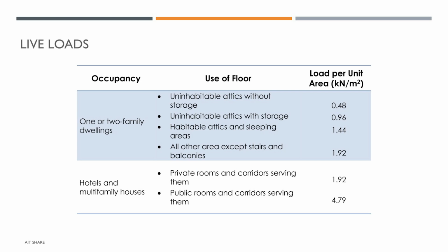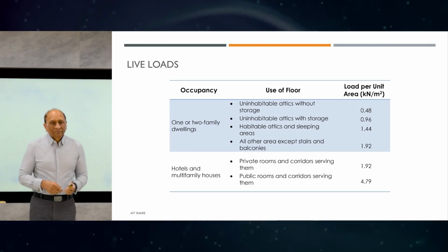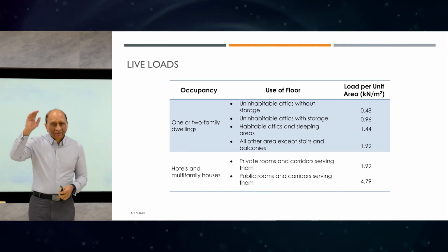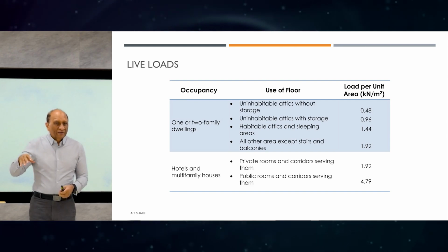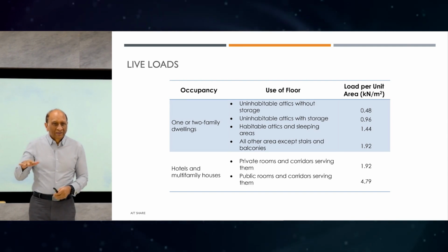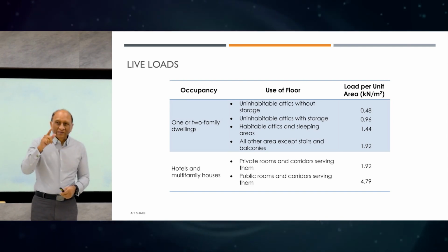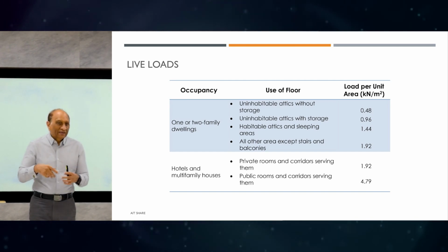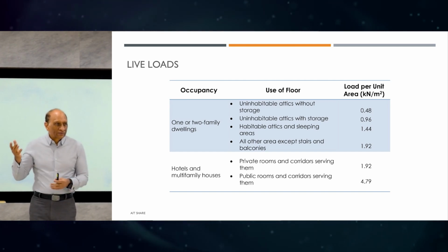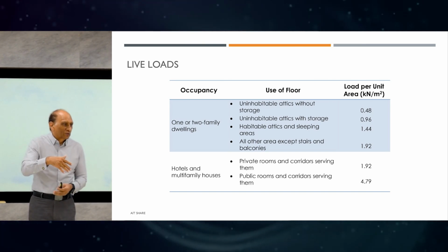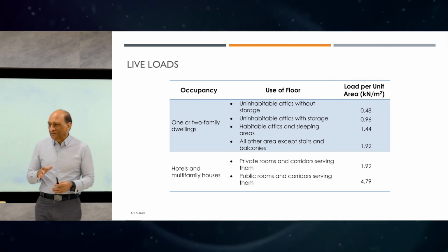Live load is a major issue in tall buildings. First of all, we talked about multi-use buildings. So each building has multiple uses: hotel, library, apartments, office, all in the same building. So every floor has a different live load specification. And the challenge comes because the building owners can change the use later. Let's say they could not sell the hotel rooms, they change it to office or something, or the office did not sell, they want to make it into a hotel now. All the loading criteria will change.